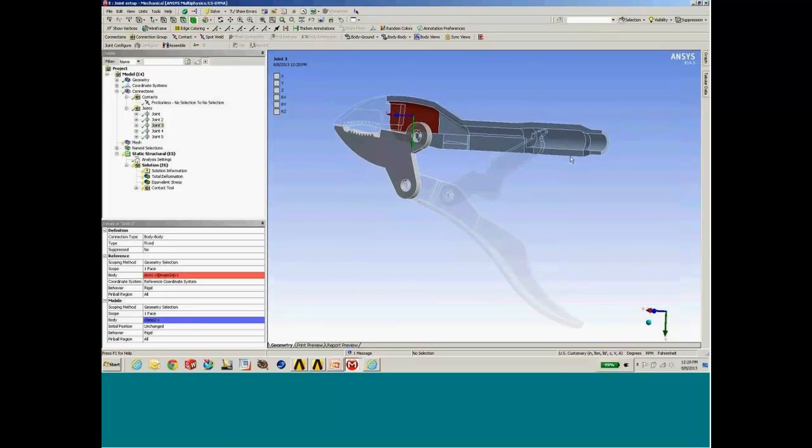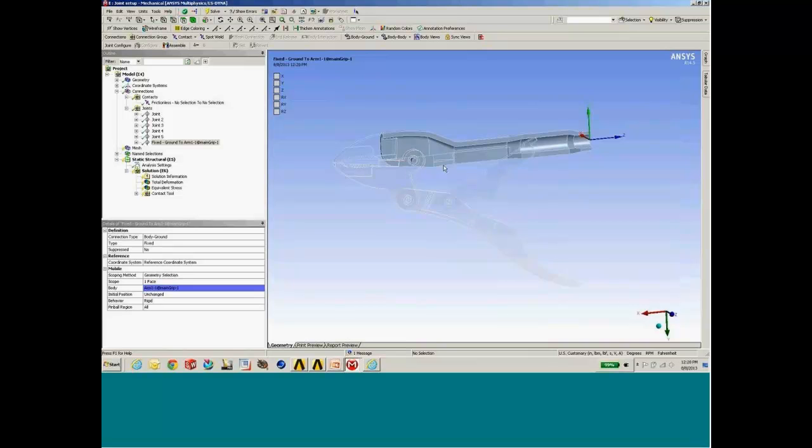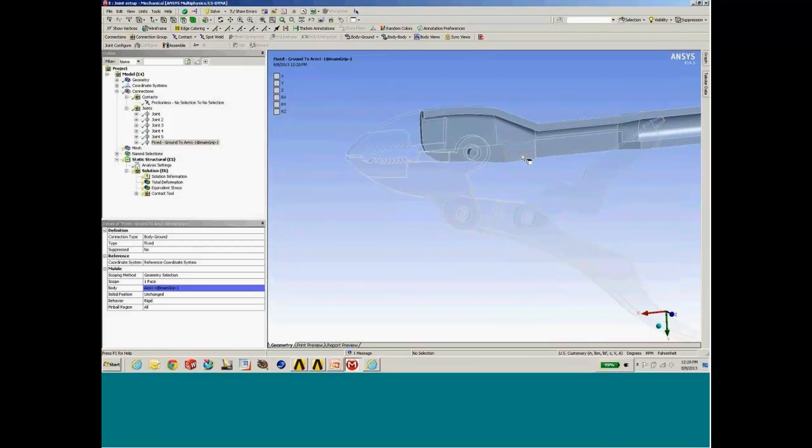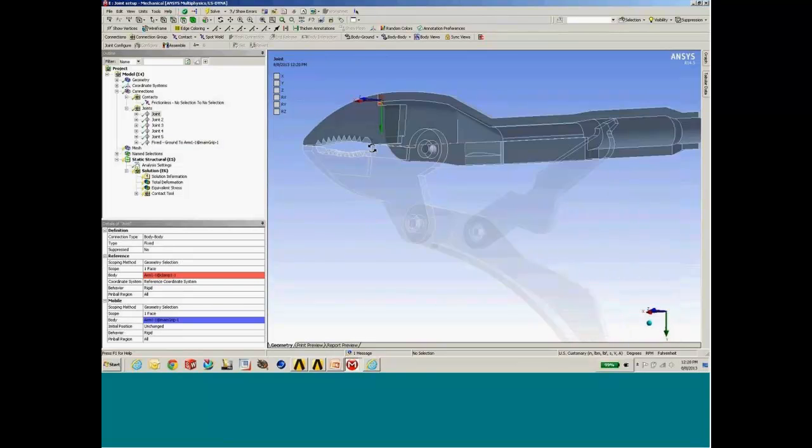So I'm going to go back now and add in that rigid one as well. So we'll pick on that face on the end there, body to ground fixed. And now we just need to treat these very much like we would the setup of a traditional contact scenario. We're going to go joint by joint, evaluate it, and see if it's what we need.